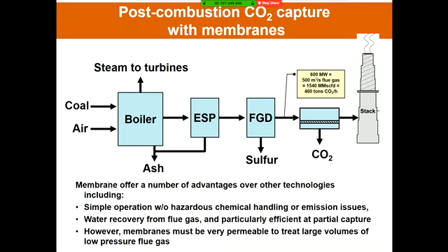If one could capture CO2 here, then it could be used for applications like enhanced oil recovery or potentially for geological sequestration. The incumbent technology to do this would be things like amine absorption. Membranes offer a number of advantages in that they don't have emissions issues. Amine plants can emit those amines over time, and membranes need to be extremely permeable to treat low volumes of gas at very, very low driving force or low pressure.